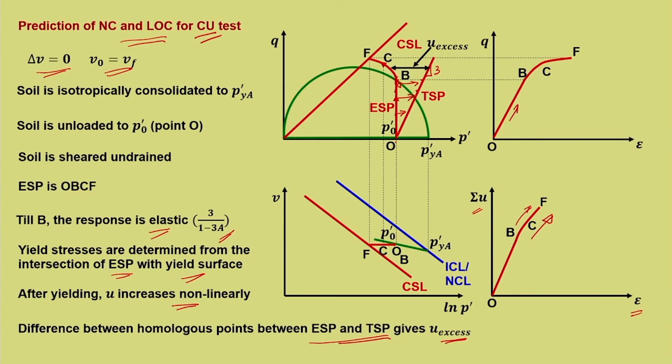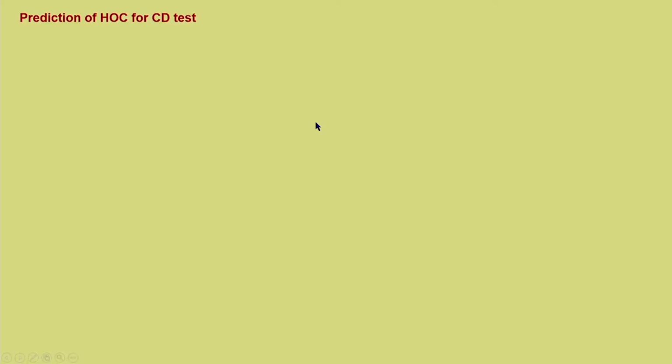So, it is very convenient to predict what kind of pore water pressure gets generated. So, that is what it means. Based on the MCCM, that is the elliptical yield curve, and the effective stress path information jointly will be able to predict the yield point and the failure point. But obviously, for all these we need to know the critical state parameters.